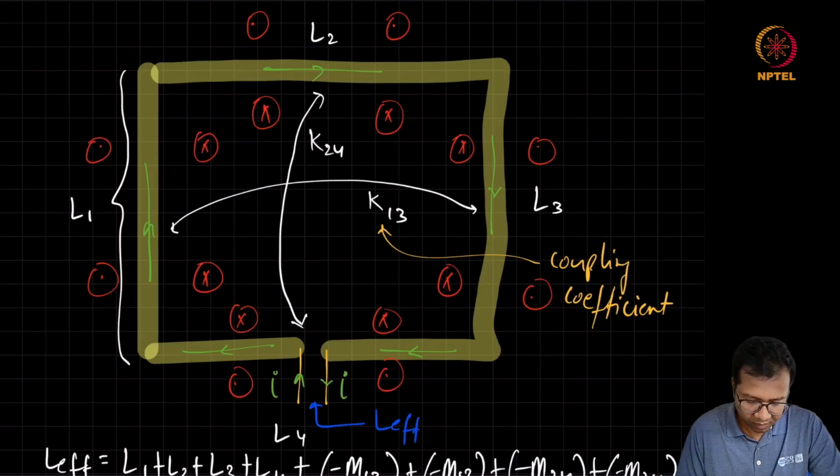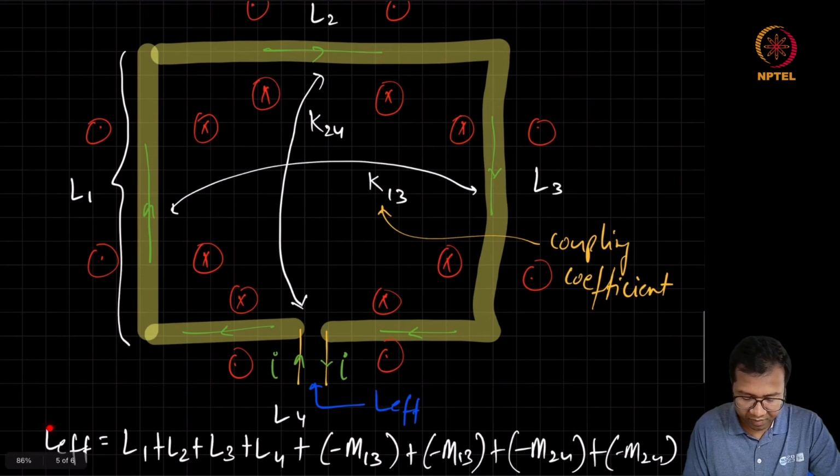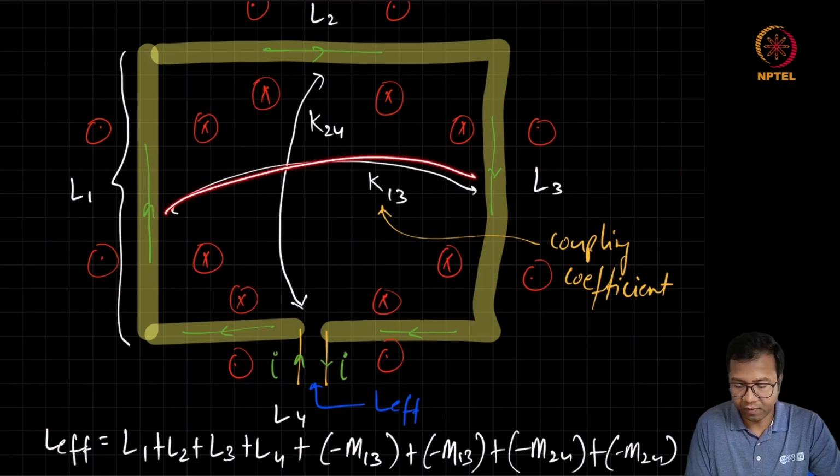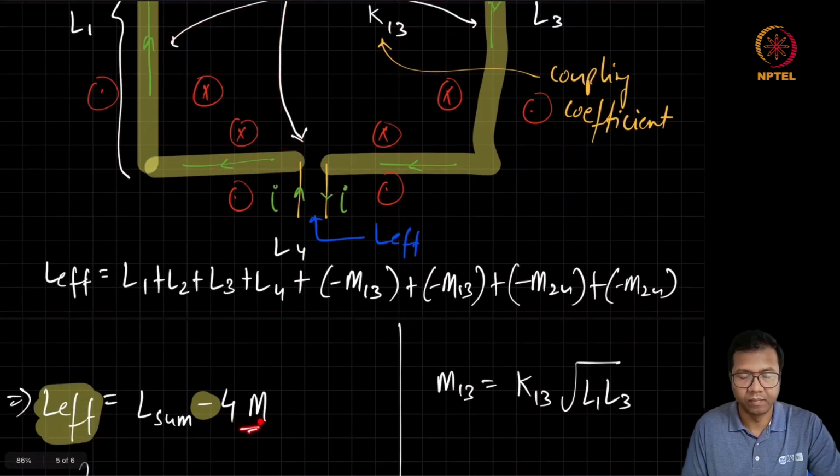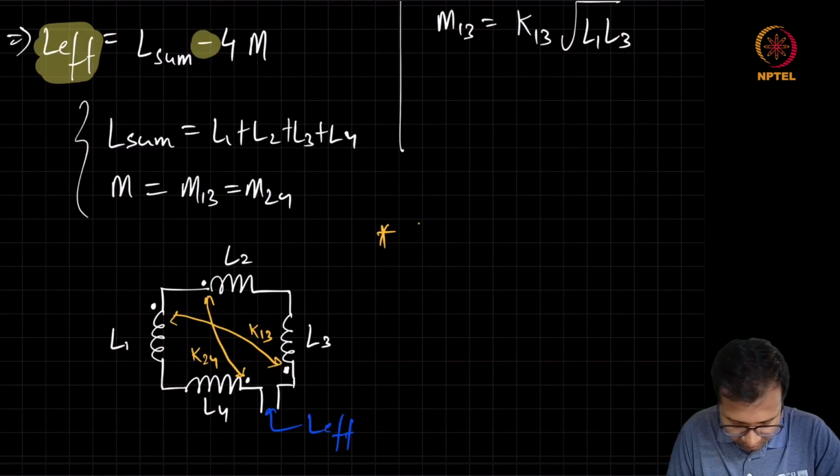The conclusion is, if you want to maximize the inductance, you should make sure these segments are as far apart as possible from each other so that this reduction in the inductance because of mutual coupling doesn't affect the effective inductance of the loop.